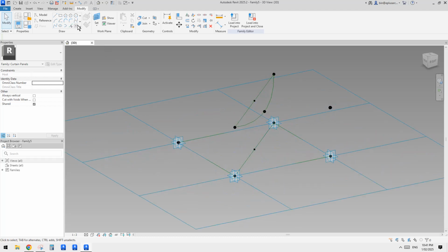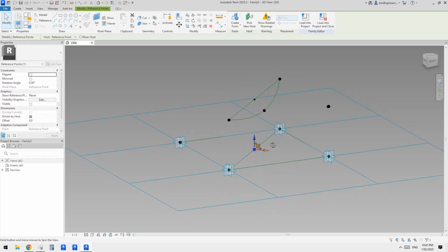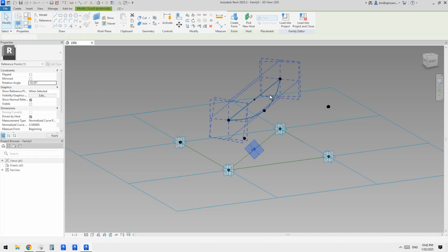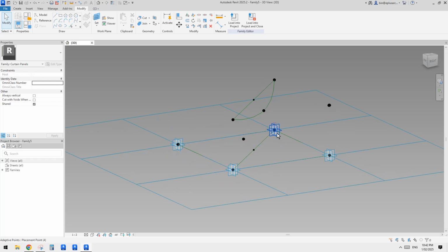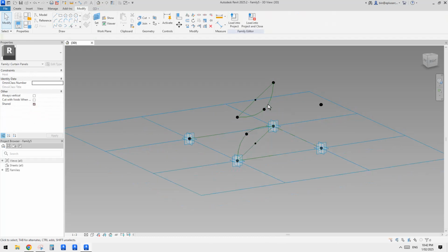And let's do the same. Point, draw on work plane, set work plane, tab. This time, maybe let's use a horizontal work plane for this one. Place it, select it. So give it 200 offset. Let's try 45 degrees on negative. Yeah, okay. So 1, 2, 3, spline through points, reference line.